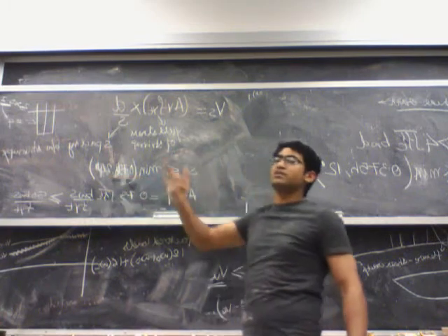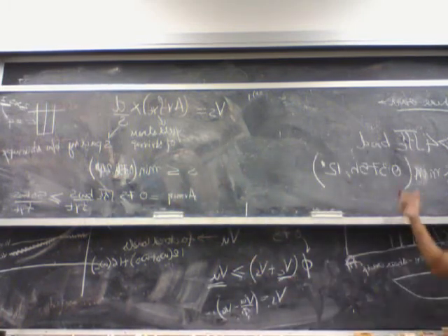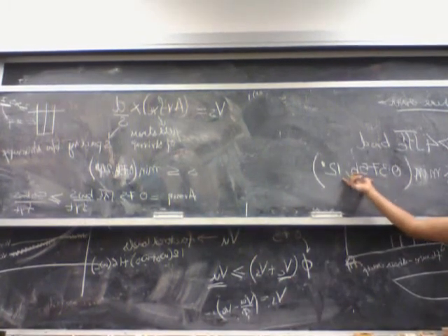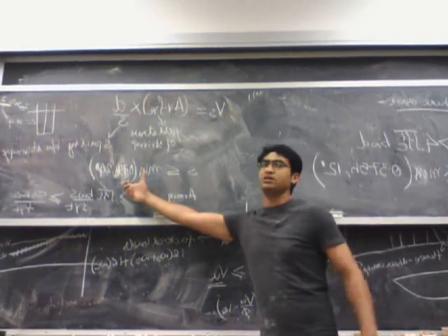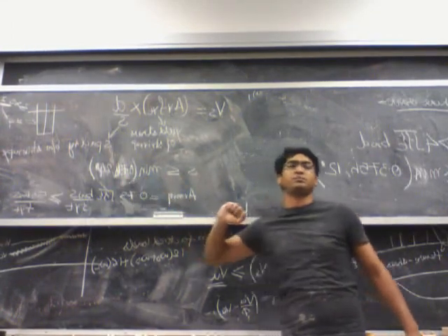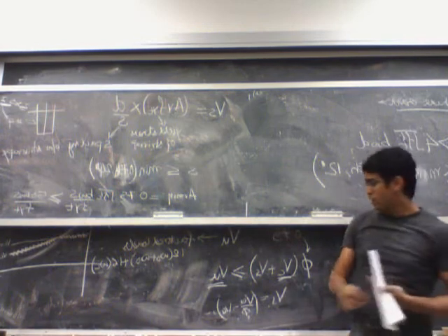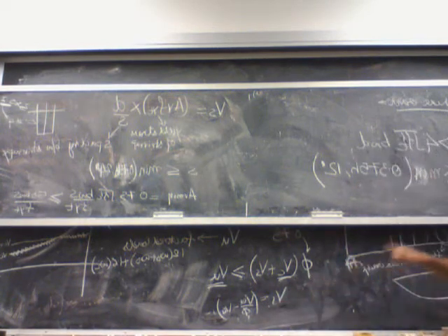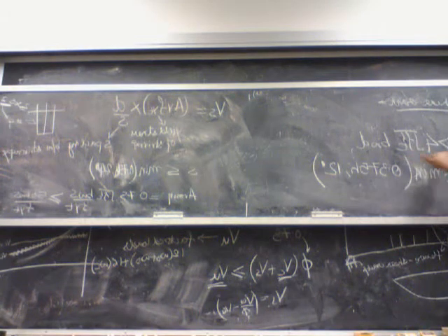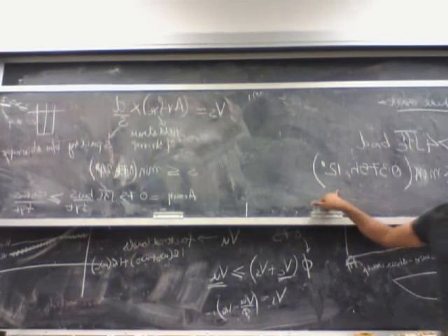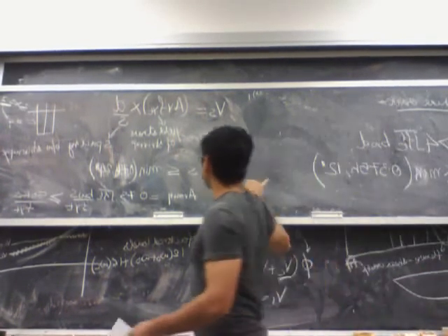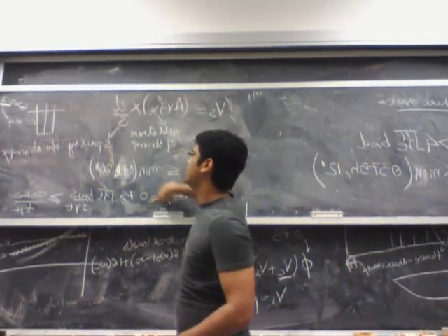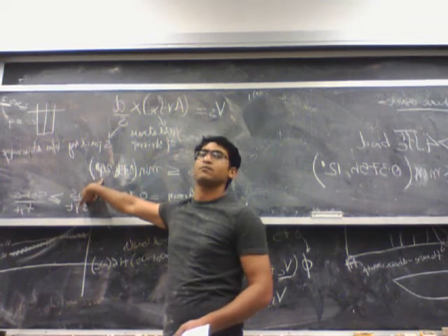So if you have more shear that has to be carried by the stirrups, you need to provide a smaller spacing compared to if you have a smaller shear which needs to be carried by the stirrups. So what you do is find the Vs. Based on this Vs, you check whether it's greater than this value or not. If it's greater, this becomes your maximum spacing. If it's less than 4 square root f'c b_w d, then this becomes your maximum spacing.